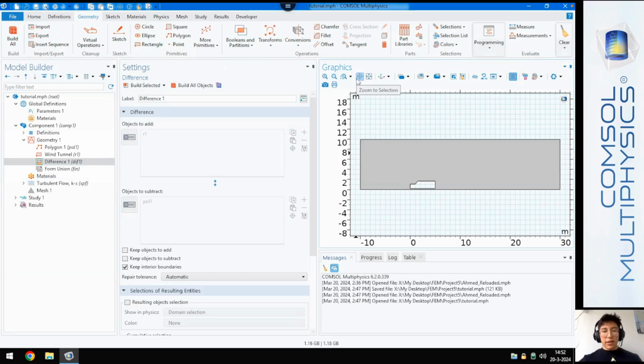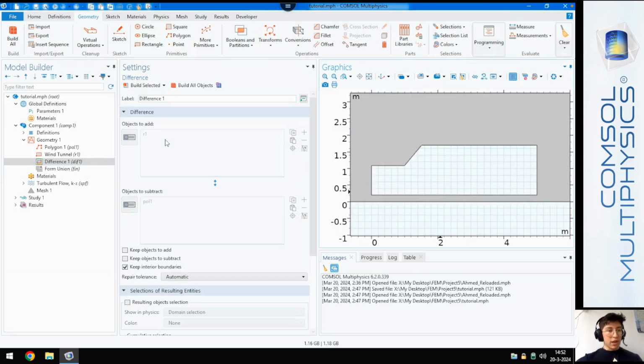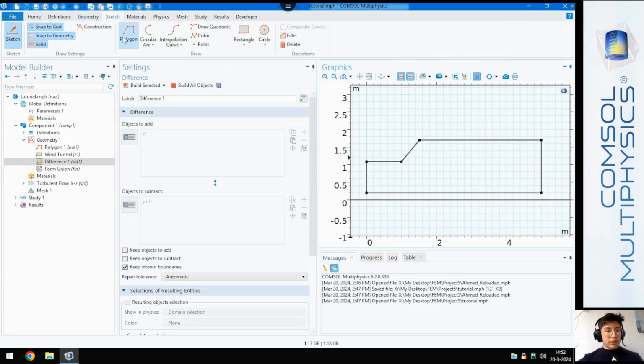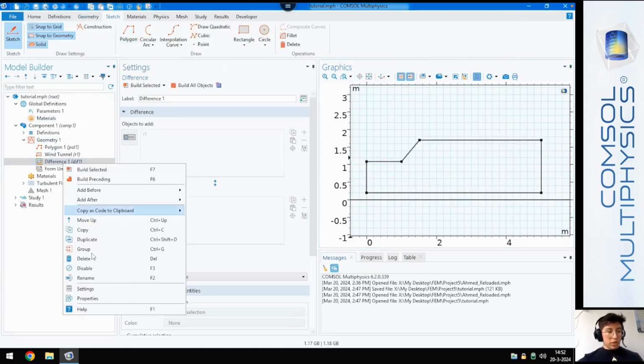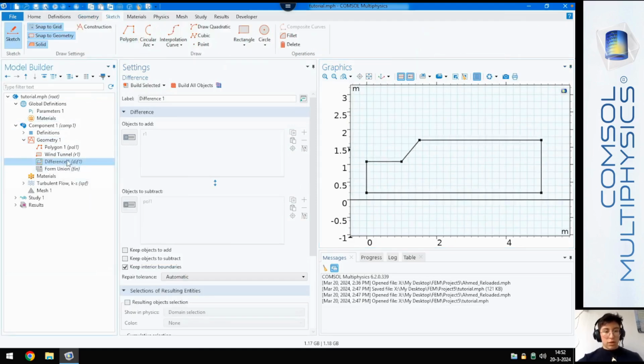However, in reality, something that you could want to do, because it does make a big difference, I've realized, is adding a fillet. So what we can do is go back into sketch mode. We're going to disable this modifier here, because when that is enabled, essentially you have already built your solids and you can't modify those. So we're going to leave that.